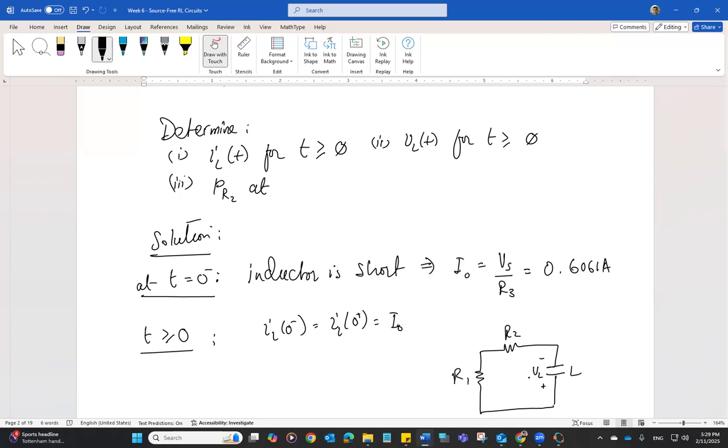So this will be the direction of the voltage across the inductor when it starts supplying the current. Current direction is not going to change. Of course, current will still be flowing through the inductor in the same direction. Through the resistance, of course, the current direction is going to be opposite because now the inductor is your source.